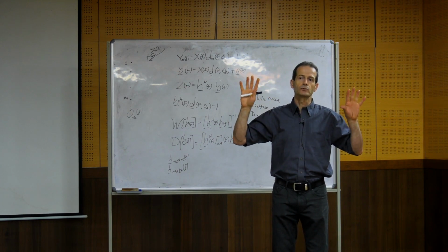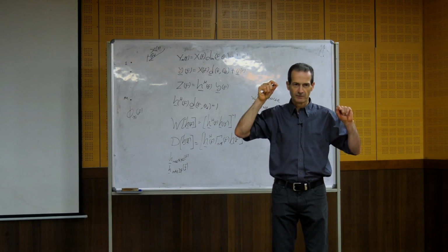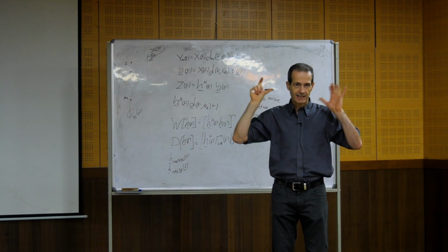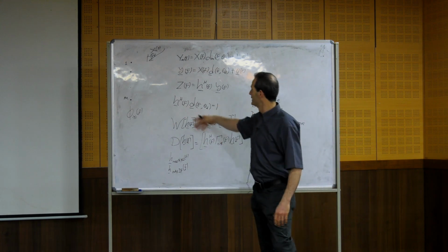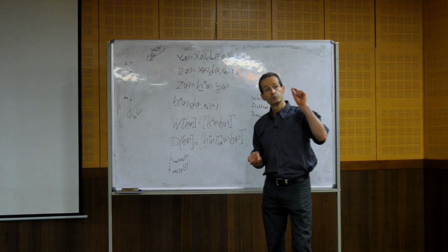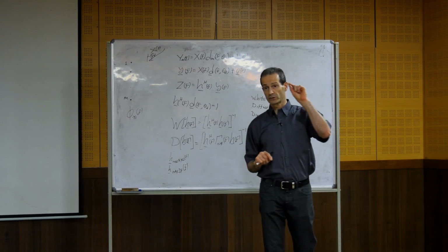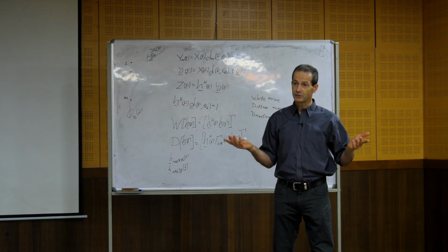So one thing is to measure the exact position of the sensors on each device, and put that in the design and include that, and also to measure the response of each sensor. So this is kind of calibration.